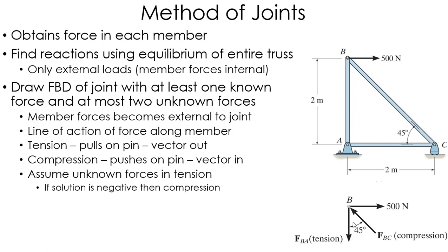That way it just keeps my thoughts very consistent, and again, if I get a positive answer, my assumption is correct. That way I always know that a positive answer is tension, and a negative answer, which means my assumption of tension is wrong, means compression. Okay, but you can really draw it any way that you want, but I always tend to assume tension, and then if I get a negative answer, my assumption was incorrect, I get compression.